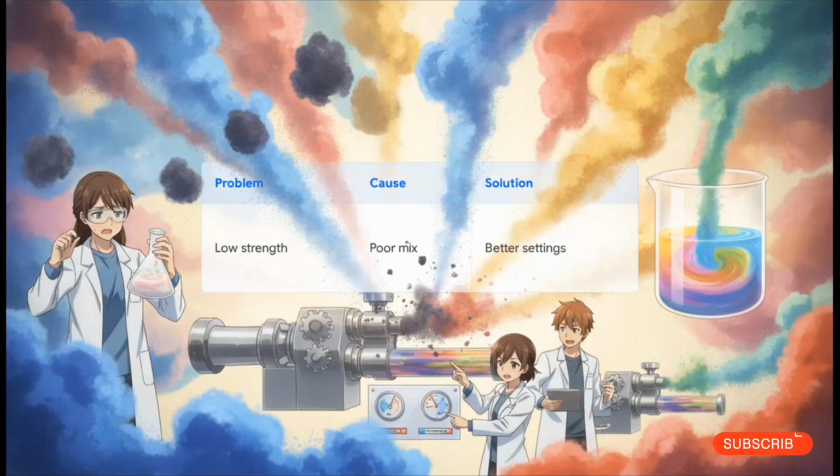And for our third case, what if your color strength is just generally low? It looks weak, washed out. Well, that means you have incomplete dispersion across the entire batch. The agglomerates aren't necessarily forming huge visible dots, but they aren't fully broken down either. There's no single magic bullet for this one. You literally need to do a full review and improve your overall compounding conditions. Double-check your RPM, your back pressure, and your temperature profile.